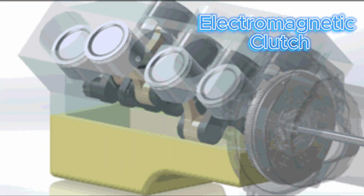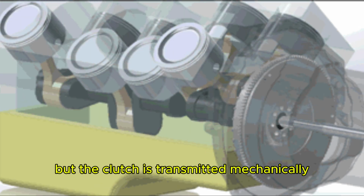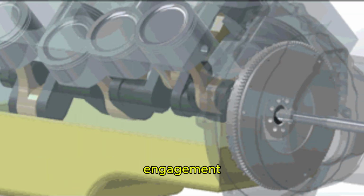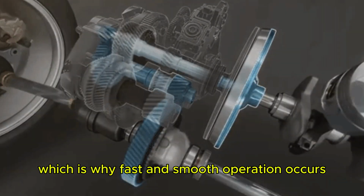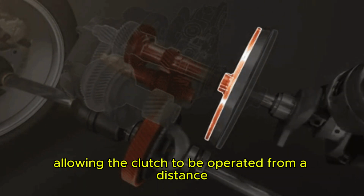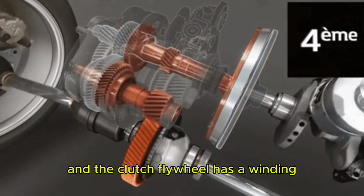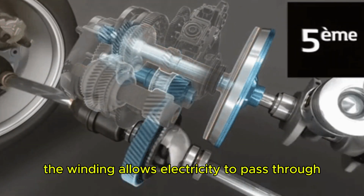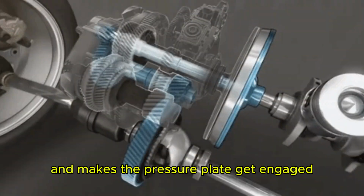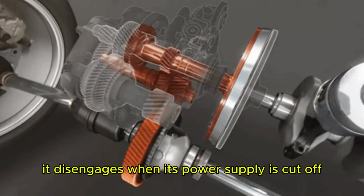Electromagnetic clutch. The electromagnetic type of clutch is operated electrically, but the power is transmitted mechanically. This clutch has no mechanical linkage to control its engagement, which is why fast and smooth operation occurs. It uses a remote for its operation, allowing the clutch to be operated from a distance. The battery supplies the electrical power, and the clutch flywheel has a winding. The winding allows electricity to pass through it, produces an electromagnetic field, and makes the pressure plate get engaged. It disengages when its power supply is cut off.